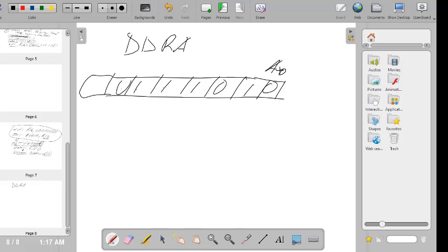All right, so we know that if I put a 0 on port A0 in the data direction register, it means this port is going to be an input port. This A1 will be an output port. This A2 will be an input port. So this will be what? The output ports. So how do we do it in assembly code?